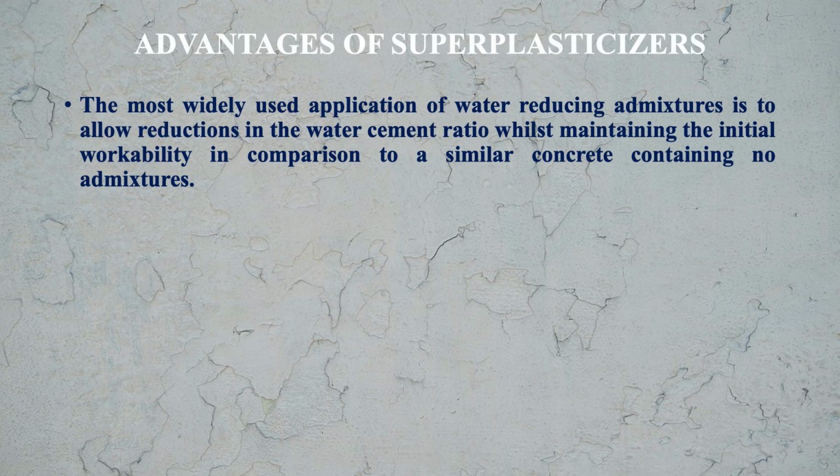The most widely used application of water reducing admixtures is to allow reduction in water cement ratio while maintaining the initial workability in comparison to a similar concrete containing no admixtures.